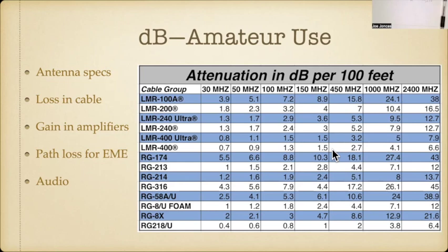Well, that's what was recommended to me, and it's a good low loss. It's a little bit more than RG8 or RG8X, but to me, it's worth it. And I use the LMR 400 Flex on the top of the antennas, so that they could spin around. I've got that on all of them, on the 2 meter, on the HF rig.